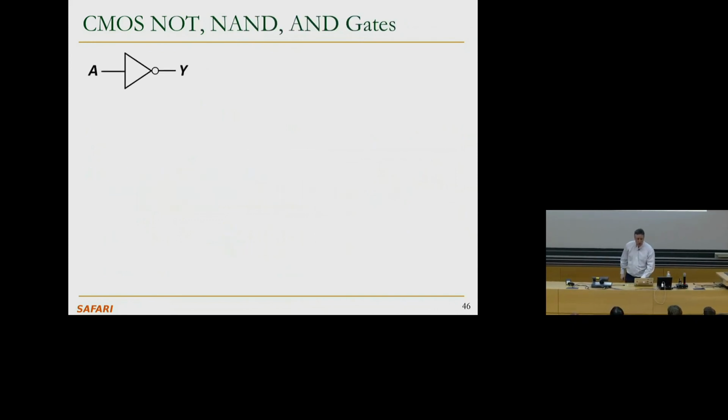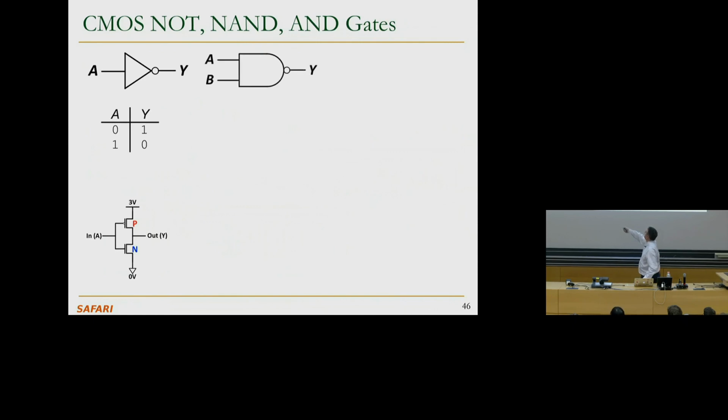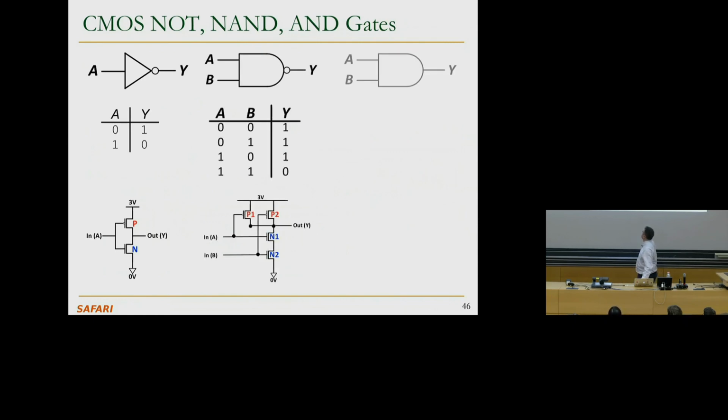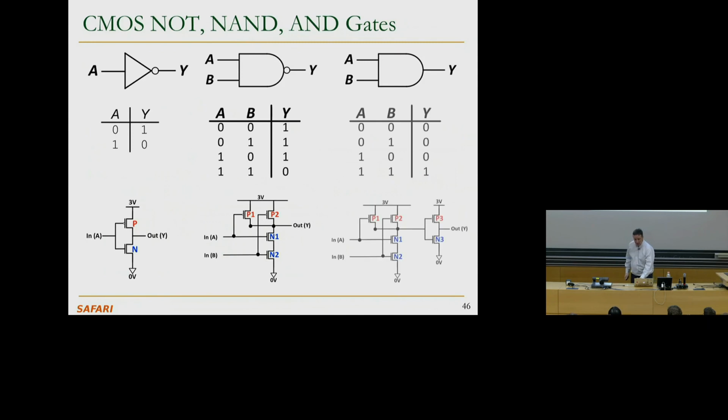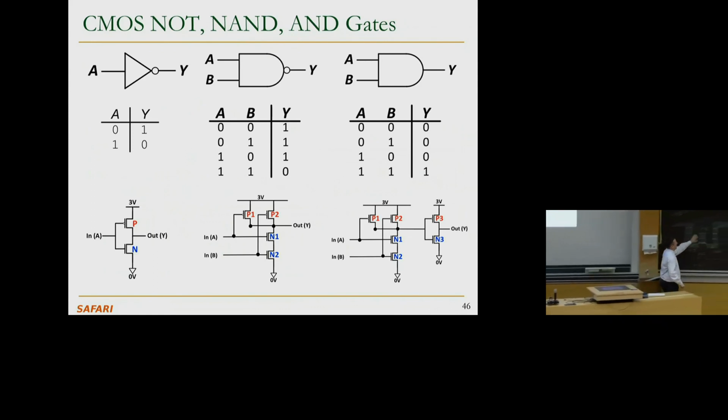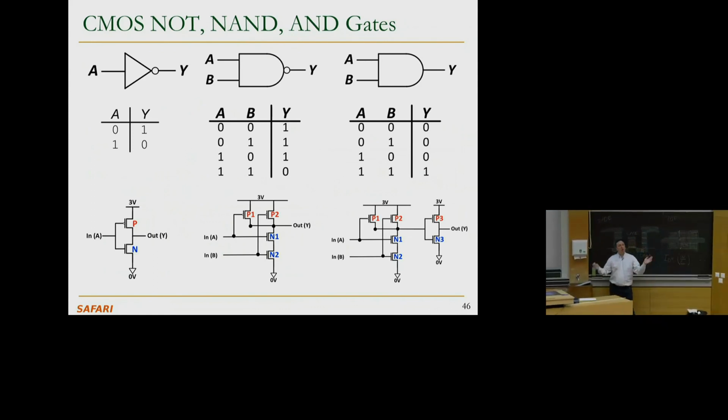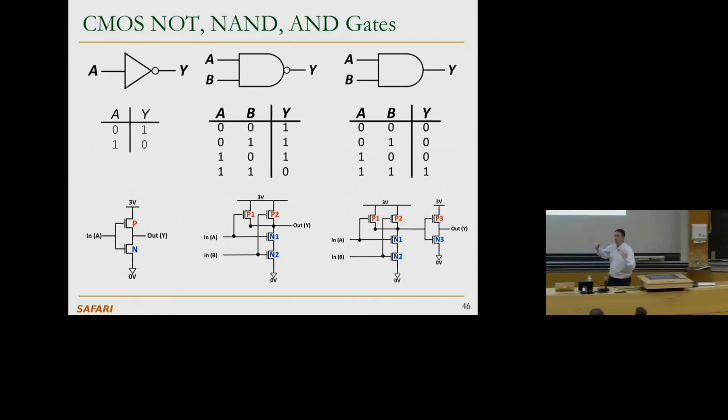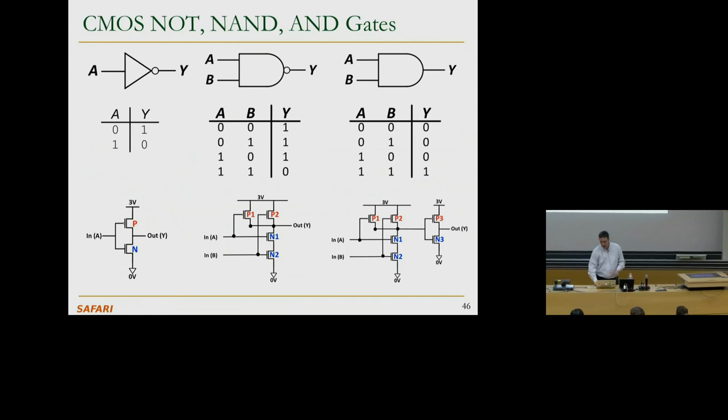So if you put all of them together, here we have our NOT gate. We started very simple. Then we started with the NAND gate. We combined them, we came to the AND gate. And this is the way we are building. And now you're also getting the idea. All of these transistors, if you look at it, they are all like the same thing. They just work as switches. We combine them in different sort of combinations. We connect their inputs, their outputs together, and we grow the functionality as we grow up.